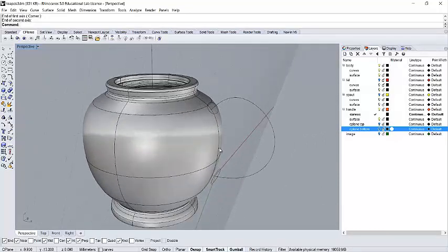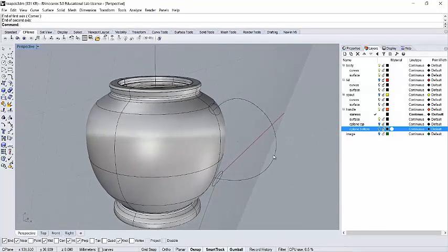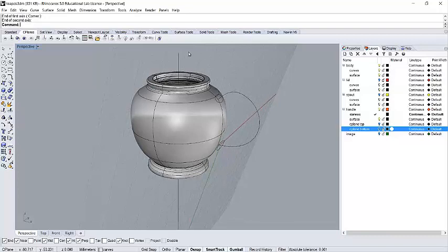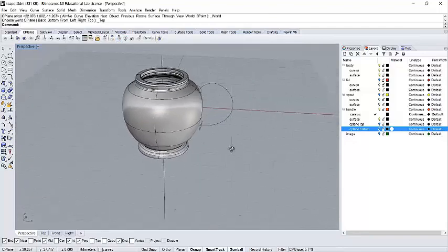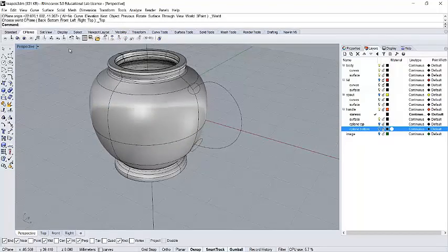I'm sure other people have got other ways of doing it, but I like the visual simplistic idea of having these little planes on turned off layers that I can turn off and on, and it's a visual clue to where the layers are, and all I'm using is set C-planes to object. One bit of best practice though is when you've finished generating using your unique C-planes, it's probably best to use this set C-plane world top again, and that takes everything back to its start point for that 3D view.